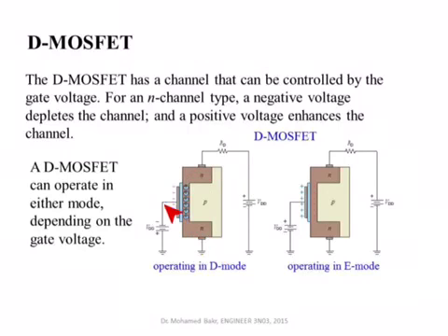But when you apply a negative voltage between the gate and the source, as shown here, you are repelling these electrons, and the more negative the voltage that you apply here, the more you are reducing conduction through this channel, and this is how you can control the value of the current flowing through this transistor.